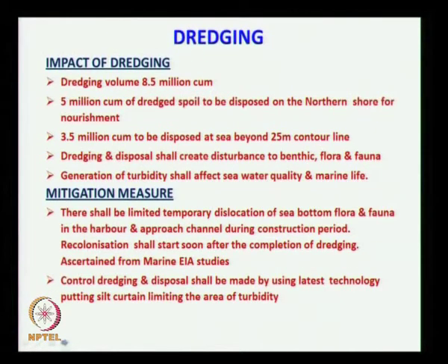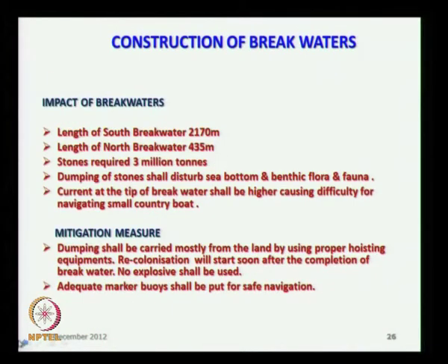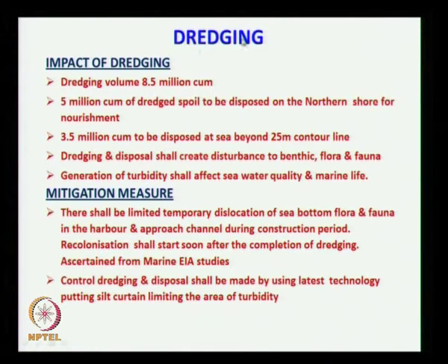Then we have one more item, that is what is the effect of dredging. There I am discussing 3 issues. One is what happens to the shoreline, what is to be done when you build the breakwater and what is to be done when you do your dredging. The dredging volume is about 8.5 million cubic meter; 5 million cubic meter is sent to the northern side, 3.5 million cubic meter at about 25 meter water depth. This dredging and disposal will also disturb and create some turbidity.